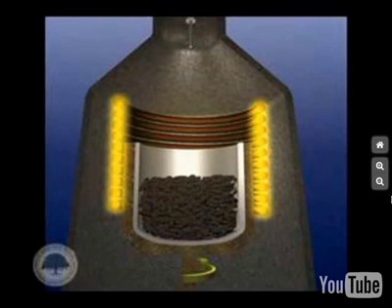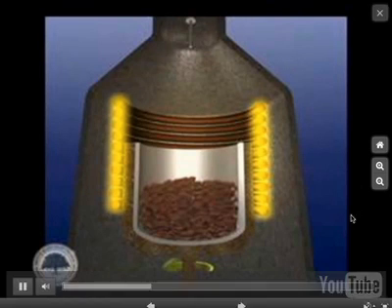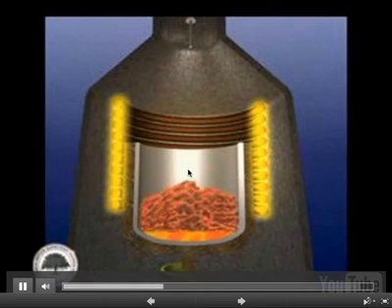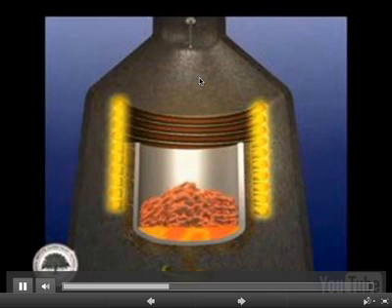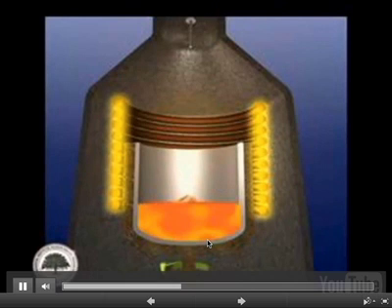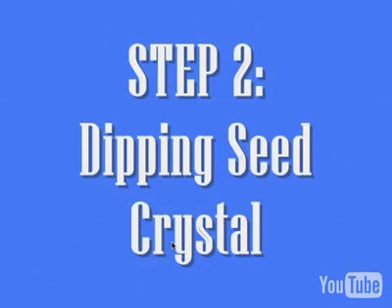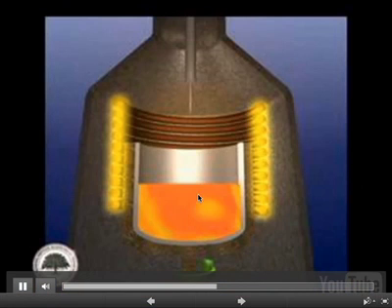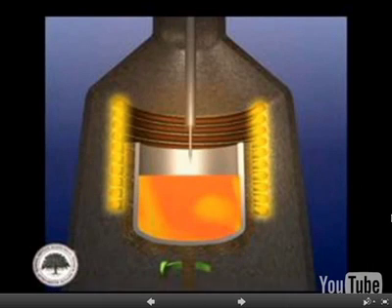Okay, so you have a furnace which heats up the silicon very, very hot. It melts here, and then you bring down a seed crystal and pull it out very, very slowly. Okay, so it's molten now. Melting the silicon is useful because it can recrystallize on a seed crystal. That's the idea. You bring the seed crystal down, and it's rotated very slowly to make very uniform crystals, essentially.